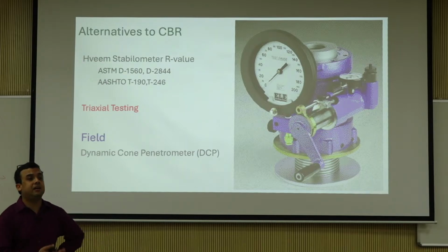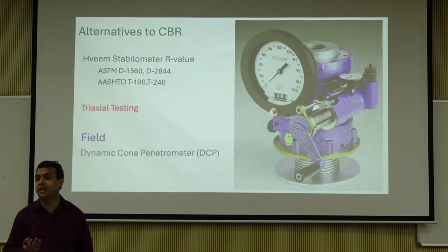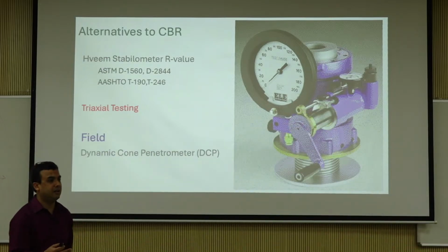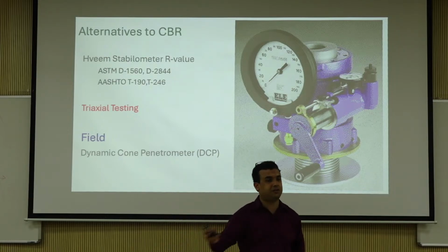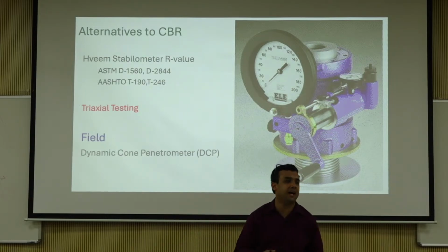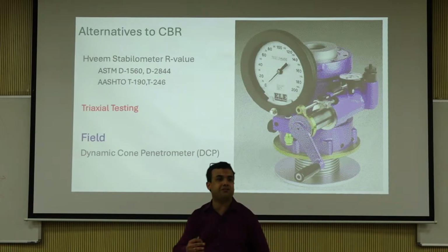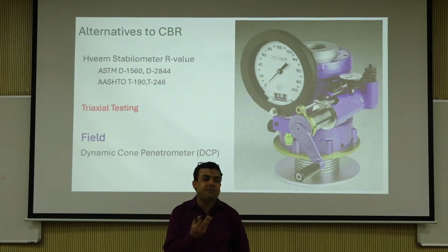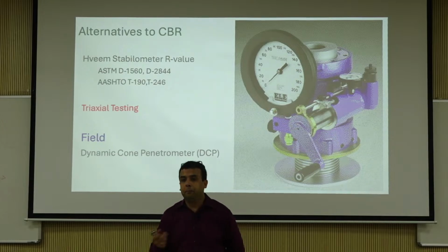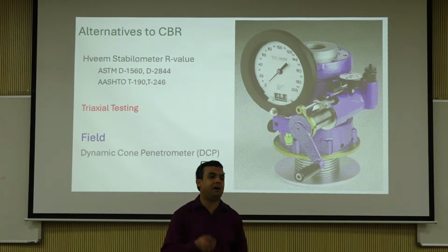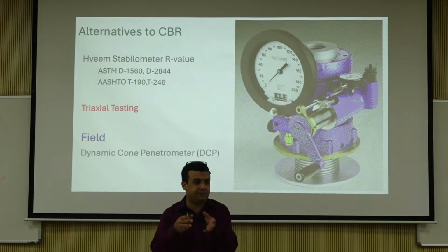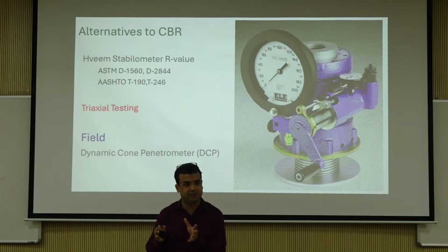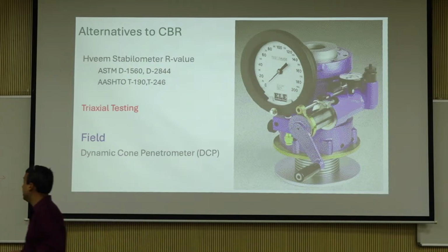That is the reason the 1500 CBR is something you can say that I have tested. Let's say there is an agency dealing with the district of Khordha, and they encounter 4 or 5 different types of soils. Over the years, they have tested and characterized the soils, and they have developed a database saying that, okay, my relationship is that resilient modulus at some stress state is about 2500 times CBR. That's okay, because they have done it for their soil. They know what is representative. We cannot use it widely. It's just not something you should be doing.